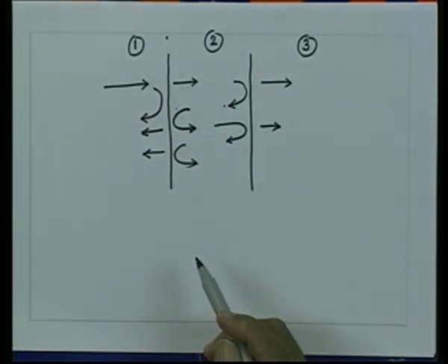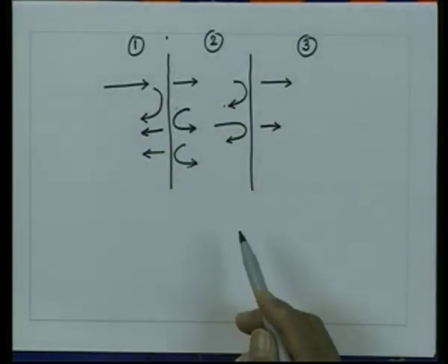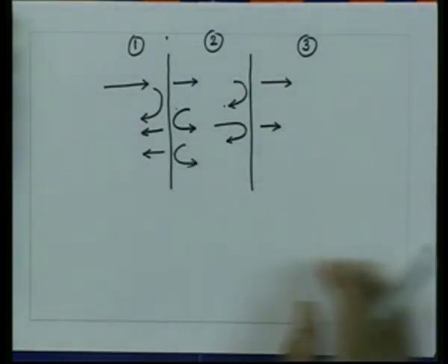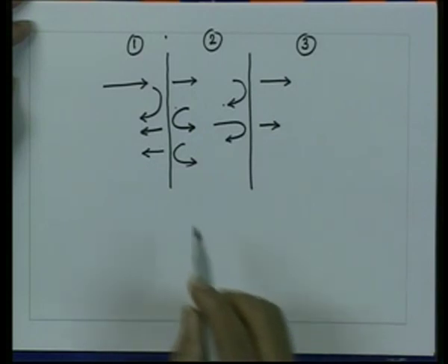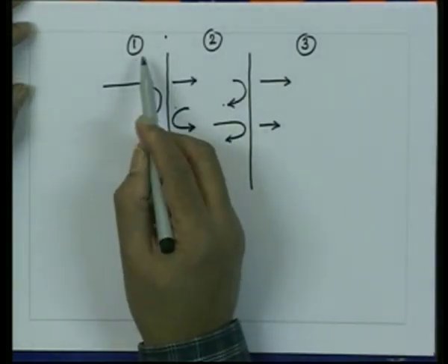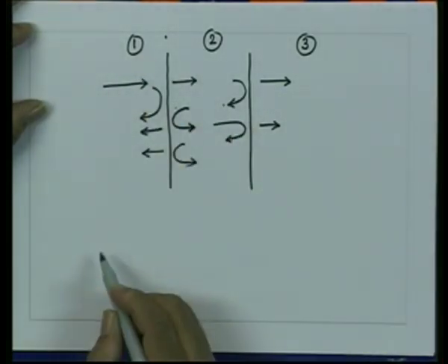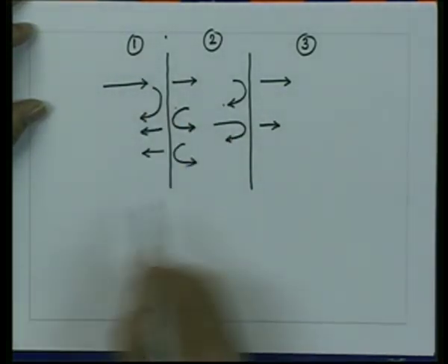So, now we can find the reflections coming from here. We can write the reflection coefficient and the transmission coefficient for each of these boundaries, find the total summation, and from there get the total reflection and total transmission. If I say the reflection at the ij boundary, so the 1 2 boundary, would be gamma 1 2.